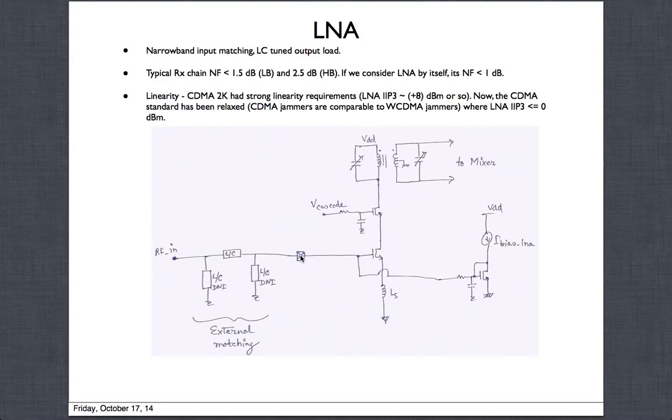Okay, the package pin itself, based on what kind of a package it is, if it's those fancy packages we have nowadays, like wafer scale packaging, then you have very low parasitic capacitances. But if you go to old types of packages like QFN or others where you actually have leads coming out, that will have more parasitic caps. So with all those things, a single element matching, what we study in theory, does not really provide good results. It will work at lower frequencies, and by low frequencies I mean maybe around 900 megahertz. Those types of bands it works.